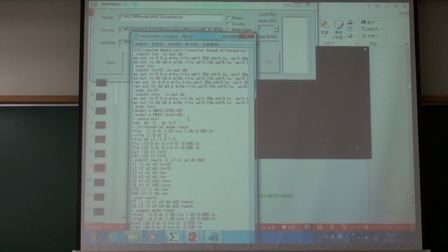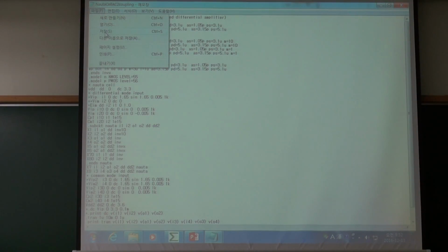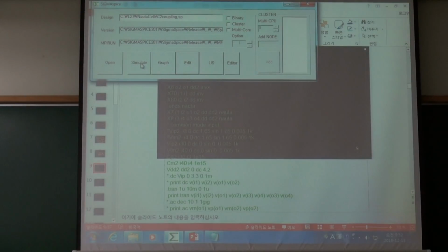All right. Let's go to the VDD2. Okay, where is VDD2? Oh yeah, here. 4.2 is pretty large, right? So if I put like 3.6, my gain will be reduced, right? Differential mode gain, because gm3 is reduced.